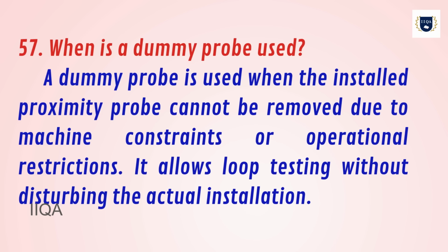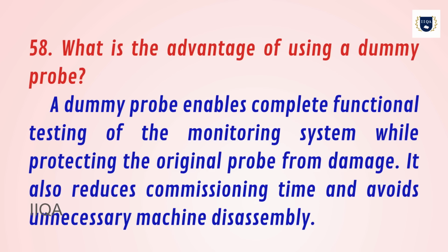57. When is a dummy probe used? A dummy probe is used when the installed proximity probe cannot be removed due to machine constraints or operational restrictions. It allows loop testing without disturbing the actual installation.